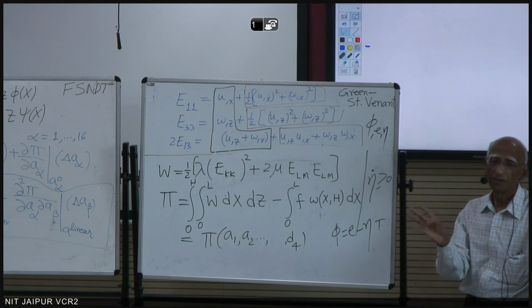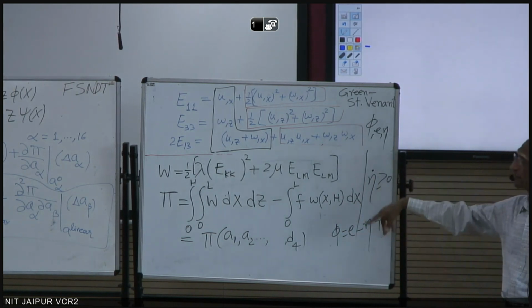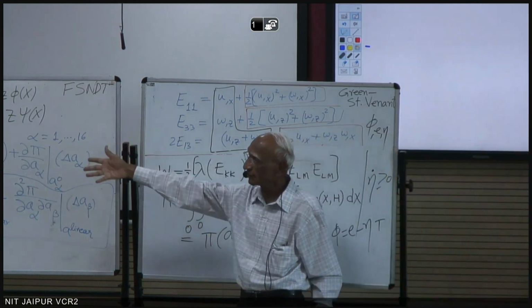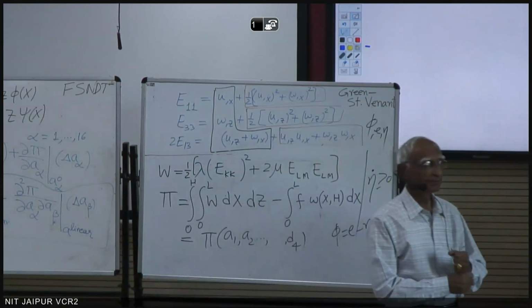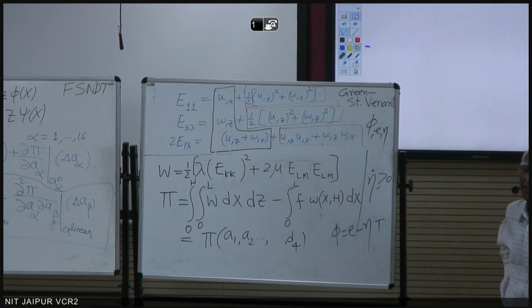It's up to you, because that's the task for the afternoon: assuming the expressions for U and W and differentiating them, finding strains, finding the potential energy, and then minimizing it either by using a program from the internet, an optimizing algorithm, or something like that. Since these are nonlinear equations, we will have to do iterations.